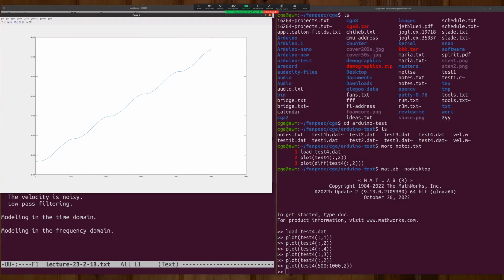So the first problem that we need to solve, or I need to solve for you, is how do we figure out what direction the thing's going in? Now, let me explain to you how an encoder works and how if we were getting two outputs out of the encoder, this problem would go away.